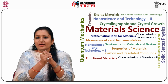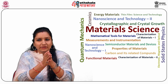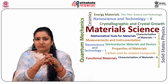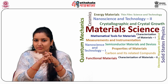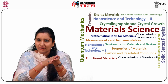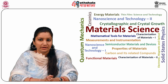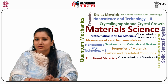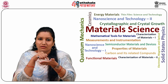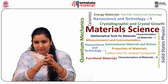Now, PLD has the advantage that it maintains the stoichiometry of the target material, thereby making it the best suited technique to deposit complex materials on the substrate in the same chemical composition as they are in target material. But the only major disadvantage it has is that the uniform deposition occurs only in a very small area, that is approximately around 1 centimeter square.